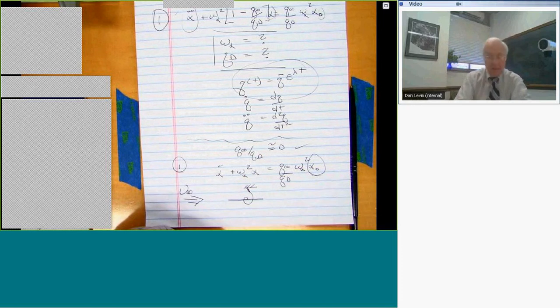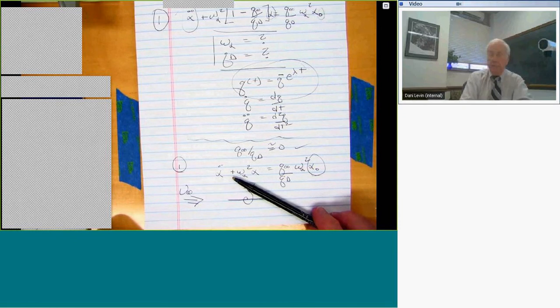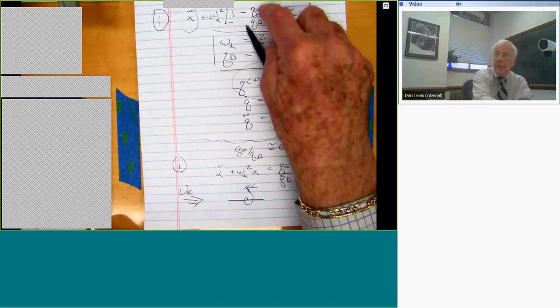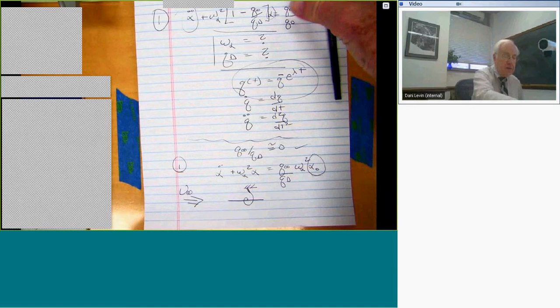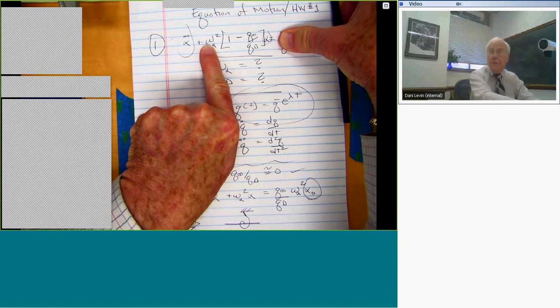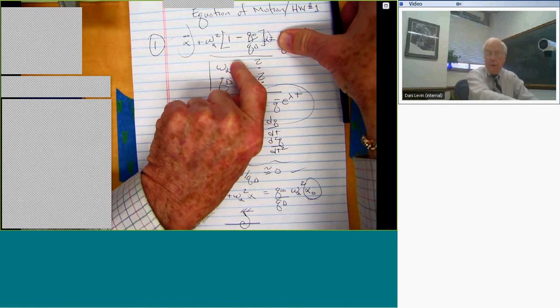Okay. But now, if I put the aerodynamics in, if I just put this term in, then the aerodynamics are forcing this spring mass system, right? If I include this term, not only is it forcing, but it's also changing the inherent dynamics of the system. There's something on the left-hand side, which is sort of a self-excitation due to the flow. There's something on the right side, which is, if you will, an external excitation. In fact, if you just look at this equation, what does this term do? It modifies this frequency. It's no longer the same old in-vacuum natural frequency. It's a new natural frequency multiplied by that coefficient.